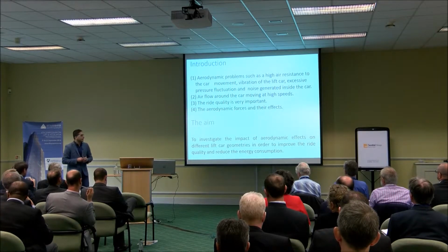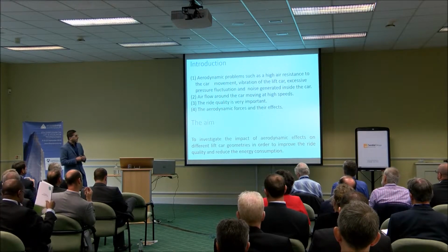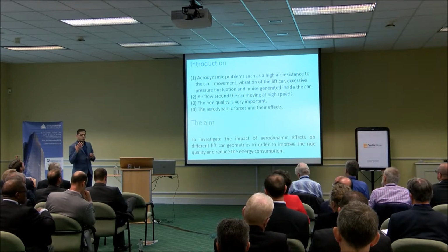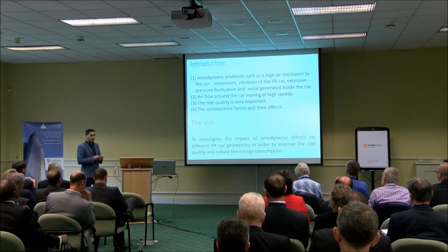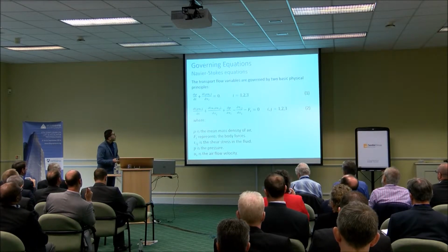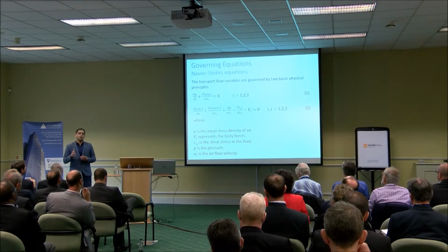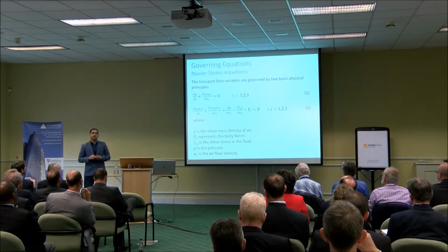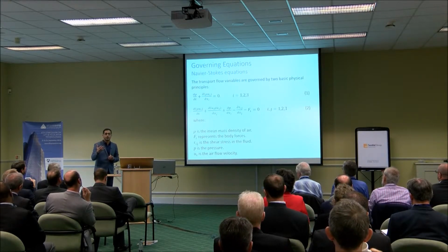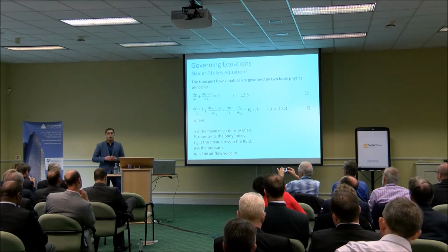The aim of this paper is to investigate the impact of aerodynamic effects on different lift car geometries and to improve the ride quality and reduce the energy consumption. A 3-dimensional incompressible Newtonian fluid has been considered in order to develop a mathematical model and also to have a better understanding of the flow.